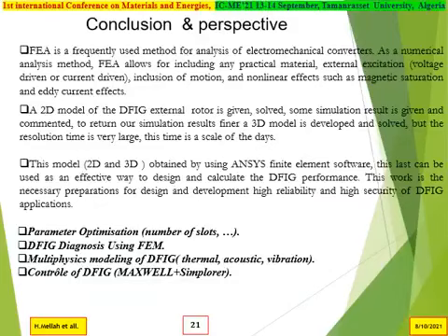As a conclusion, finite element analysis is a frequently used numerical method for the analysis of electromechanical converters. Finite element analysis allows for including any practical material, external excitation, voltage driven or current driven, inclusion of motion, and nonlinear effects such as magnetic saturation and eddy current effect, like in our model where we take into account the eddy current, the magnetic saturation and the motion.